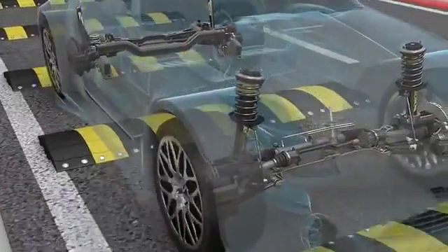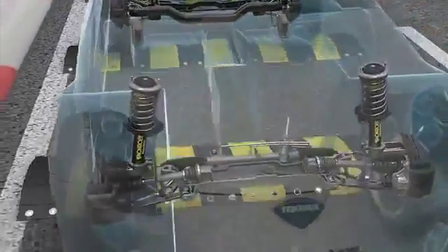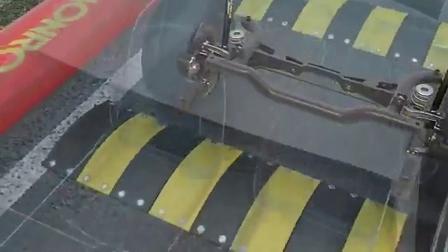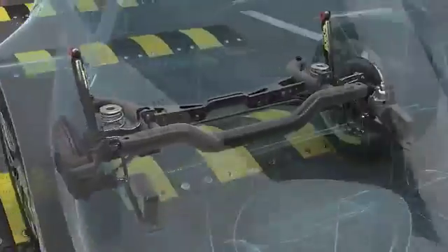In the case of the gas twin-tube shock absorber, the low-pressure compressed nitrogen gas prevents the formation of air bubbles, which produce the aeration problem and also their negative consequences for vehicle safety.